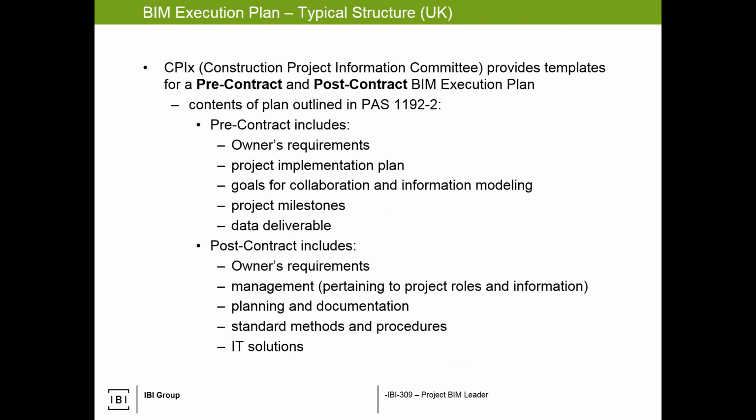In the UK, they have a template as well. It's shepherded by the Construction Project Information Committee. So the CPICs, and they split it up in two ways. They called it a pre-contract and a post-contract. And their PAS 1192, which is part of BS 1192, splits it into those two.